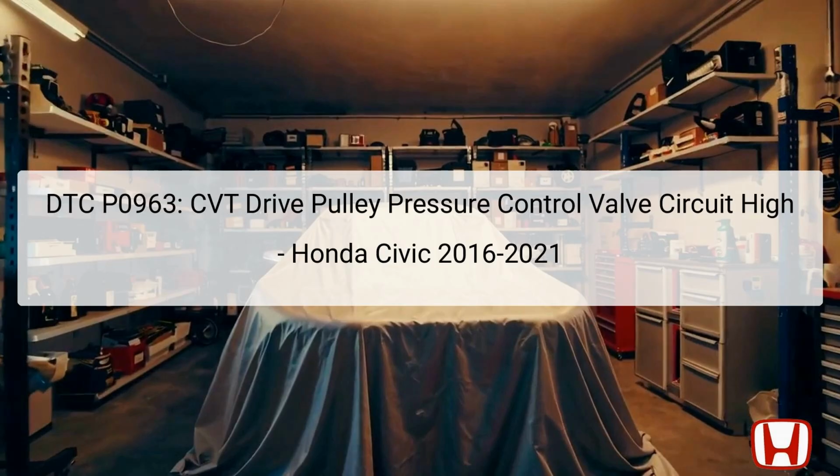The drive pulley pressure control solenoid valve plays a crucial role as it adjusts hydraulic pressure based on the commands from the transmission control module, TCM. The location of the solenoid valve is within the transmission assembly, making it critical for the effective operation of the vehicle's transmission system. If this valve fails, it could lead to transmission slippage or poor acceleration. Understanding this error code allows technicians to accurately diagnose and address underlying issues affecting overall vehicle performance.